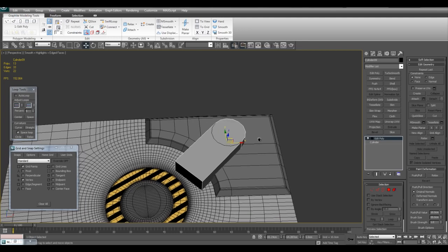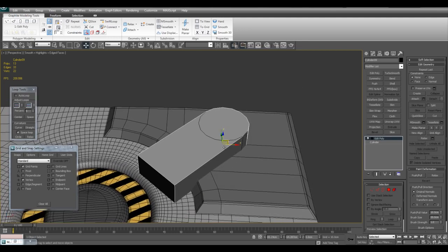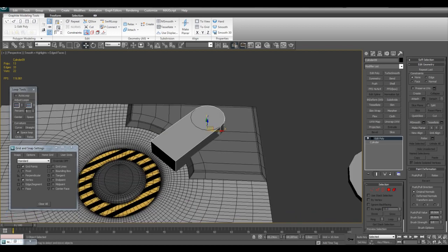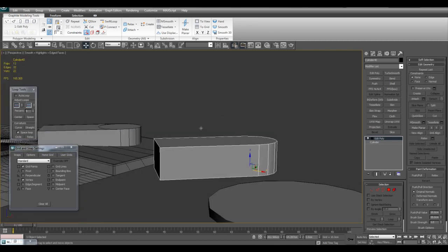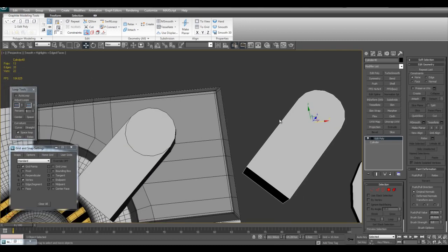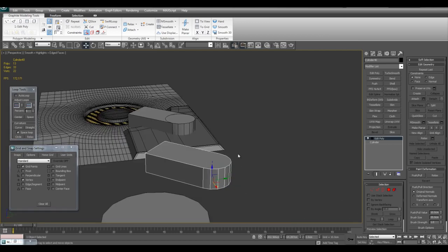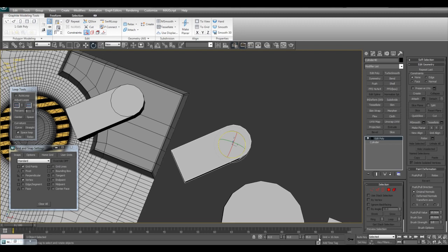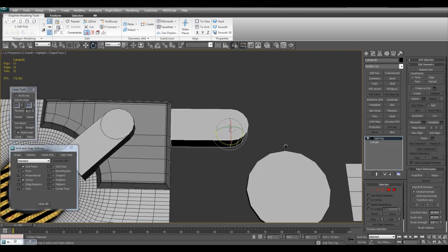Because whenever you use booleans, you want to make sure that the objects are airtight. There's no holes in them. And I will clone this off to the side once again for future use. This is a handy object to use in Boolean operations, and it's great for design work. This kind of half cylinder that's coming out here, and I can always zero out the Z rotation to have this kind of effect.